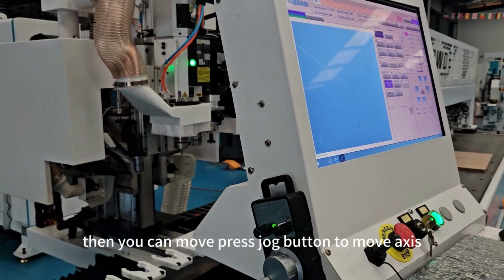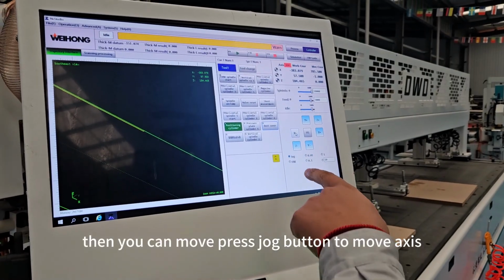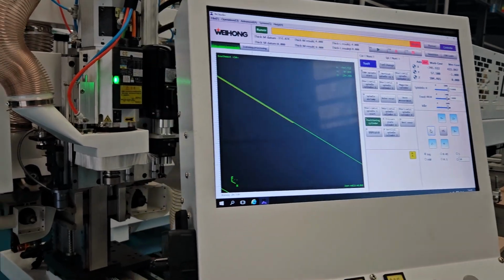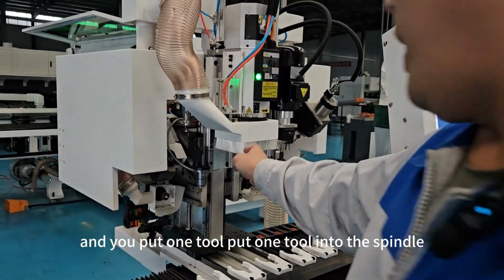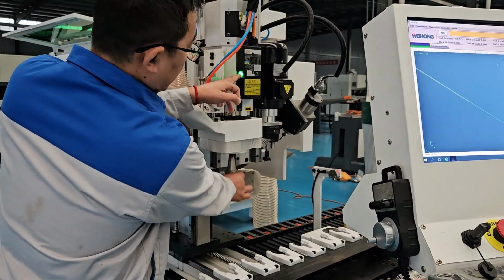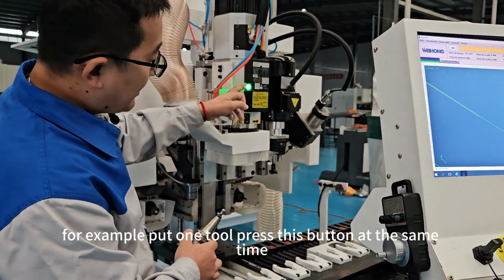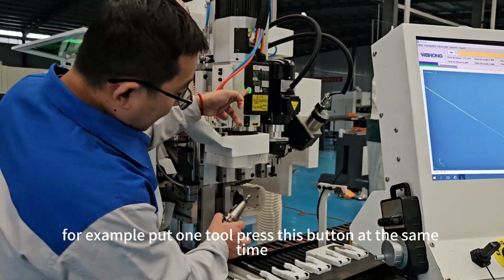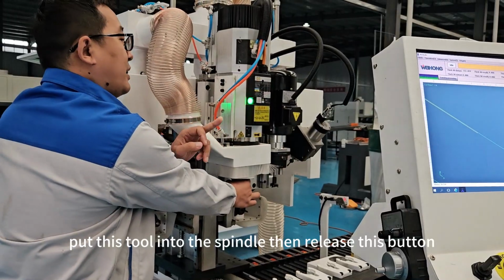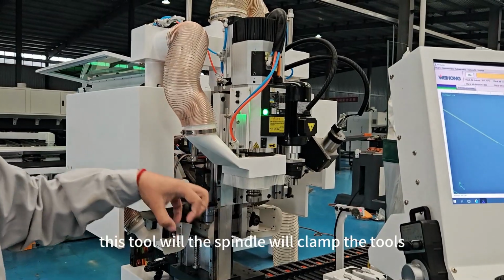Then you can press jog button to move axis to be here, and you put one tool into the spindle. For example, put one tool, press this button. At the same time, put this tool into the spindle. Then release this button. The spindle will clamp the tool.